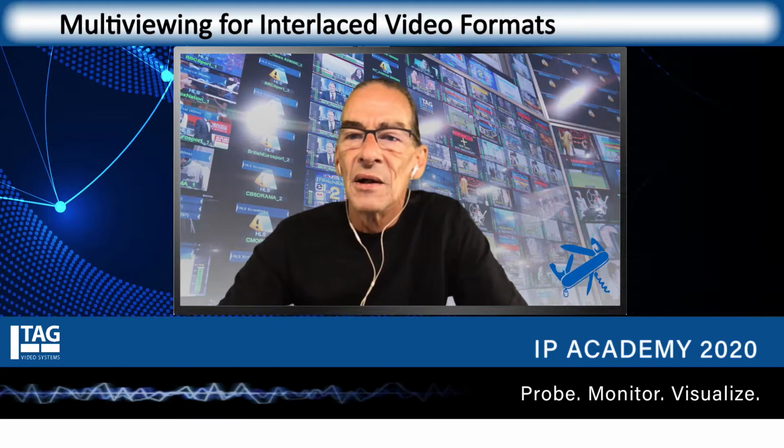Now, this little trick brings with it some difficulties. In a world where you're scanning from a pickup tube to a cathode ray tube, this works beautifully. There's nothing in between. But we don't work on these half images in real life. We work on full frames of image. You take a photograph with a camera, or you take a frame with a TV camera, forgetting for a moment that there were, of course, interlaced TV cameras. We work with full frames. So as we approach more modern times where images are now progressive and we try and deal with them in that way, and we deal with them inside computers and memory and so on, we need to find a way to get in and out of this interlaced format.